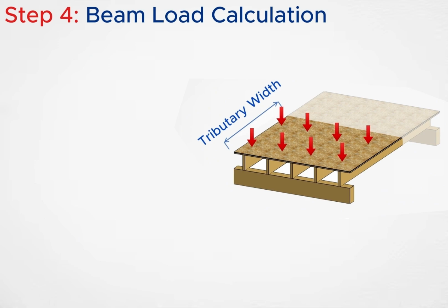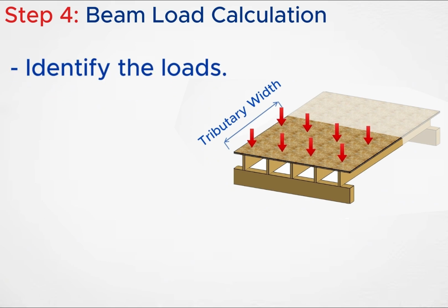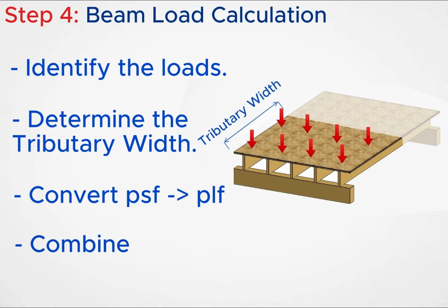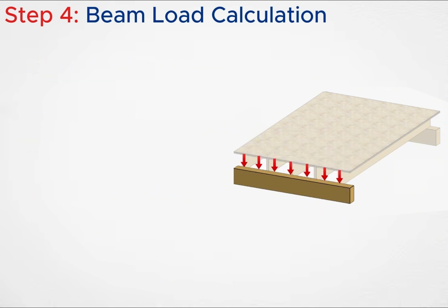So here's the workflow. Identify the loads. Determine the tributary width. Convert each load from PSF to PLF. Then combine them to determine the beam load. Load, tributary width, beam load. That is the foundation of beam design. Now we know the load acting on the beam, but what does that load actually do